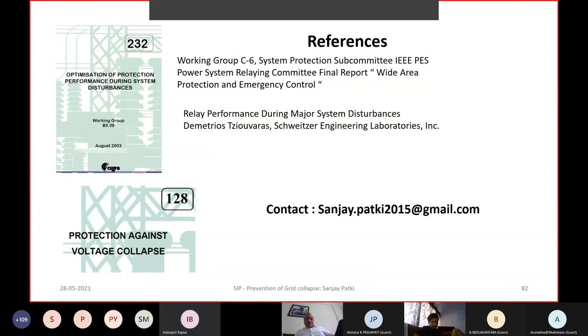See, this reverse zone, which is treated as a backup to bus fault protection, cannot do the same high speed clearance of the fault as the main bus fault protection will do. So it is a backup. The time delay should be less than zone 2 at the remote end.